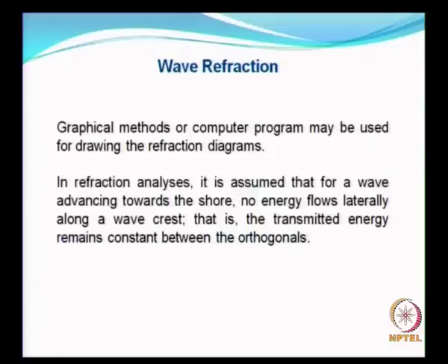As I said earlier, graphical methods or computer programs may be used for drawing the refraction diagrams, and all the other points also have been discussed. No energy flows laterally along the wave crest, that is, the transmitted energy remains constant between the orthogonals. All these points are extremely important.